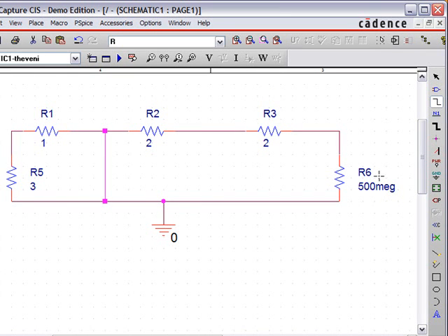Okay, and then instead of this resistor, we will just put a current source of 1 amp. So we'll measure voltage across this current source, and voltage divided by current, which is going to be 1, is going to be our resistance basically.